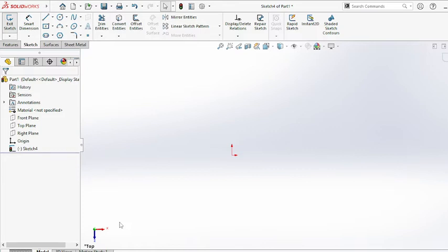Zoom in, zoom out. Okay, so selection mode also same. Okay, blue box, green box. So you can drag right side, you can drag left side. Okay, this is the difference: the blue box only selects the objects you completely select, green box selects everything you touch.